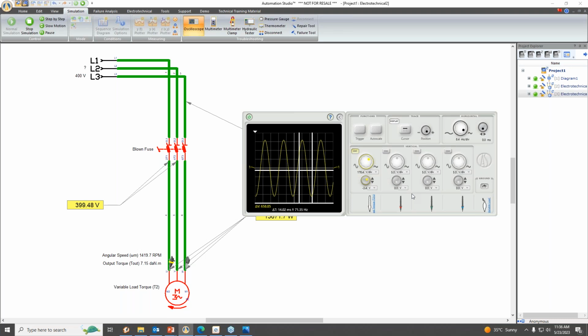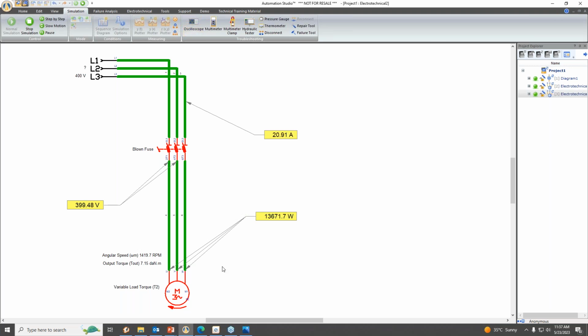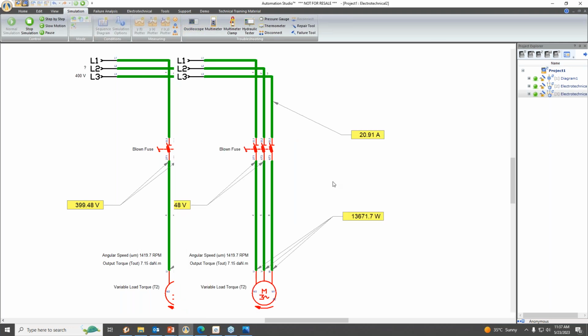So this is how an oscilloscope will help you check the properties with the help of the cursors or wavelength form. Even here you can see the delta voltage is showing over here. Delta t, the time, is shown, and also the frequency is shown. So this was the basic AC circuit which I have built in order to show the properties of the oscilloscope and all three measuring properties we have. How to measure it, we have seen.